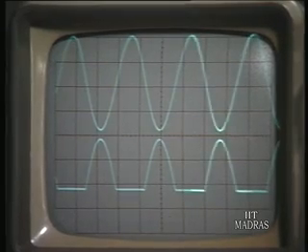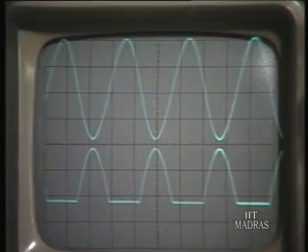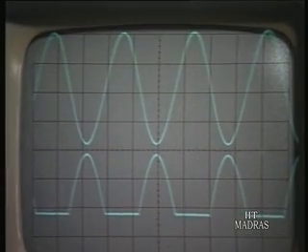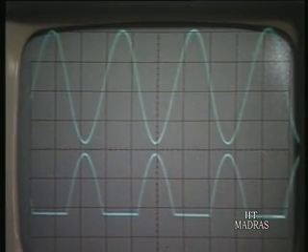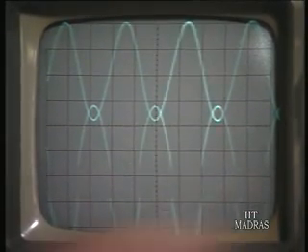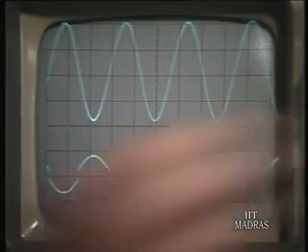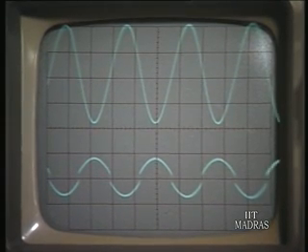You can see now this is going positive, the other one was going negative. So you can get two half wave rectified waveforms here clearly. And if you now see the output of the op amp, please show the output of the op amp. The output of the op amp, you can see it is jumping and following the input.